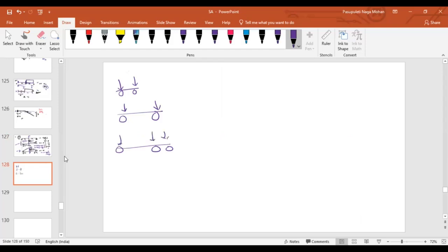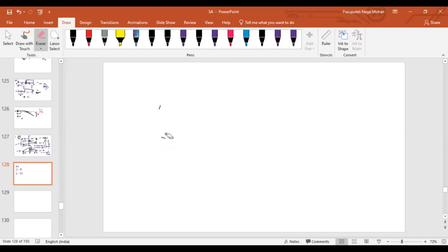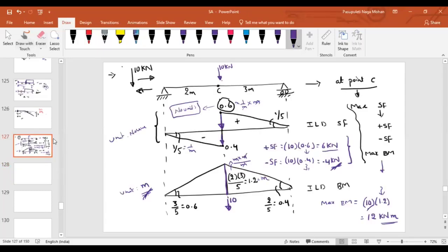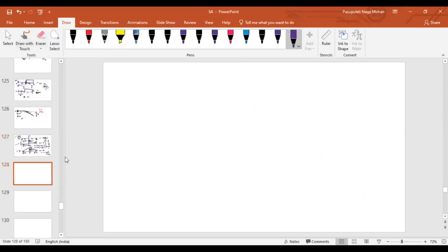so for different types of vehicles, different combinations of loads are possible. So that's why, for different possibilities of loads, we have to try to get the conditions to get the maximum corresponding values. As of now, let's just keep this aside and talk first about the UDL case, and then we'll talk about the combination of the loads later on. Again, I am considering the same beam.